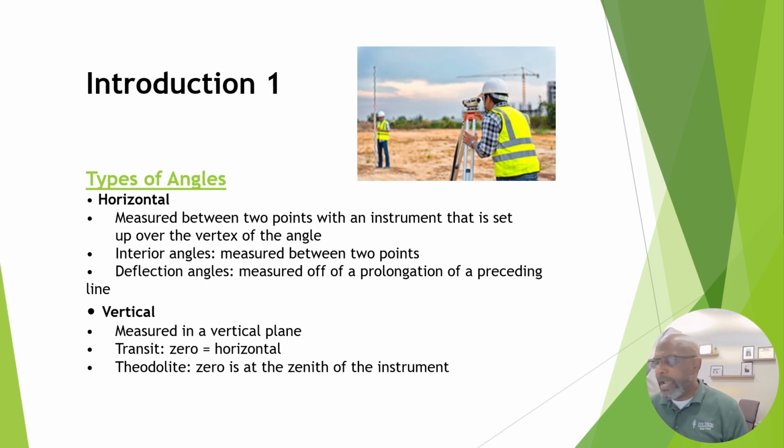Horizontal angle measurement occurs on the angle measuring circle, which is independent of the vertical sighting. In other words, it stays stationary as we move the scope around. And this is with any type of scope that we are using. It doesn't matter if it's a transit, or some optical or digital control. This is explained more thoroughly later as we go along in this chapter, but as we look at it, we're going to talk about different types of angles.